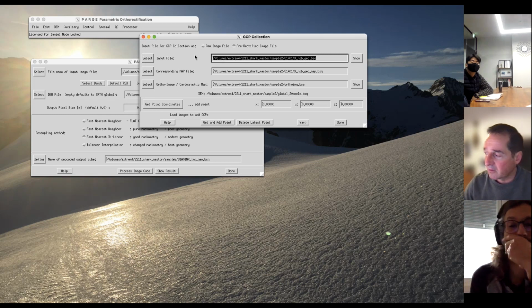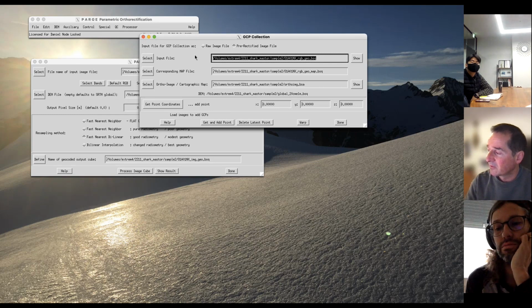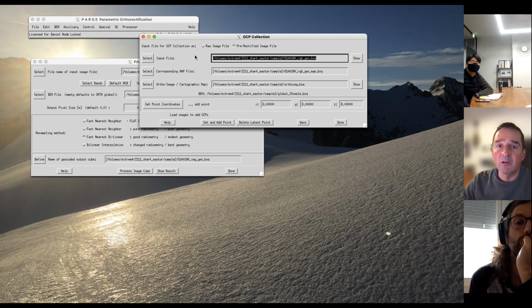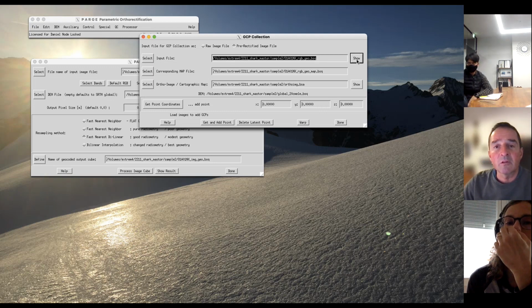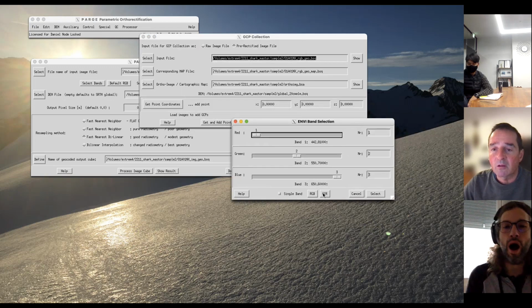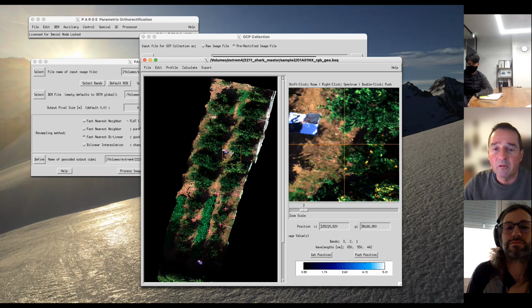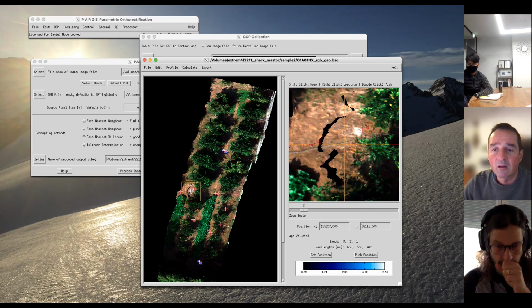So I did a first run of rectification before. So it was just a preliminary rectification. This is already rectified but not geocoded. It's much better to search for GCPs if you have a rectification done.